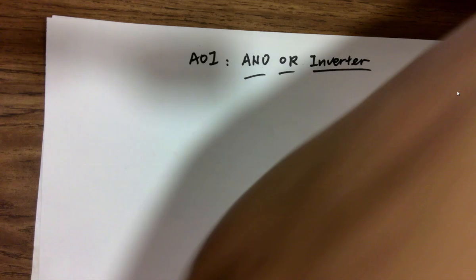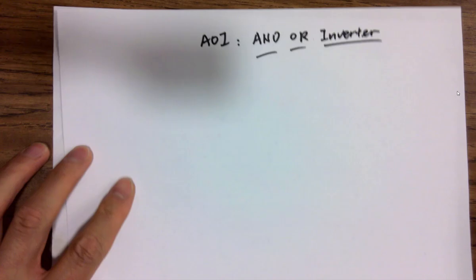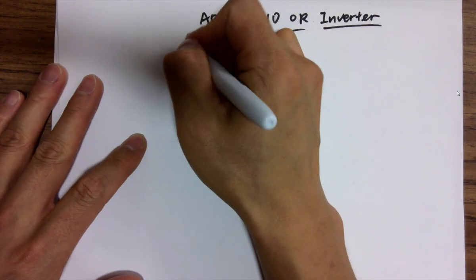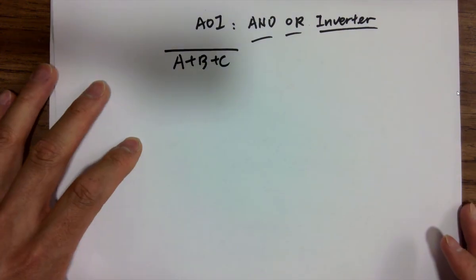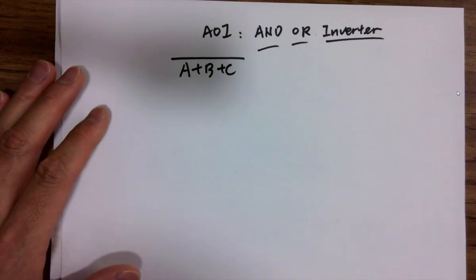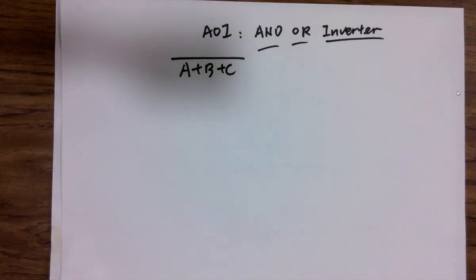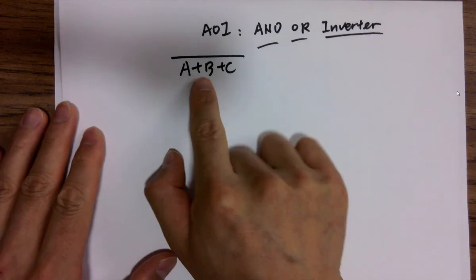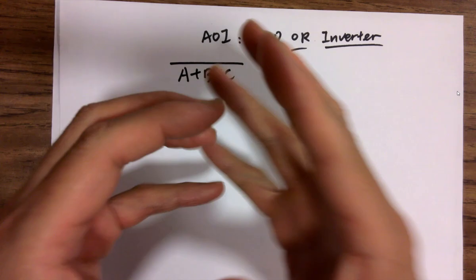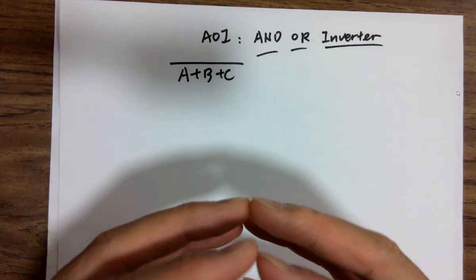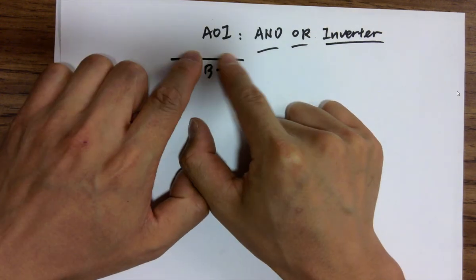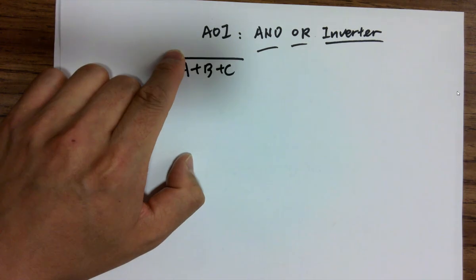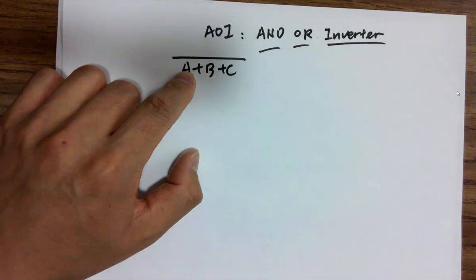Now let's look at more examples. If I have A or B or C, this is pretty simple. How this works: always think about the NAND and NOR schematic. Okay? Whenever you have a logic expression, for the future, the first step is you convert everything to one logic expression and have a universal bar on the top. And then you convert it back. Then you look at that logic and find out the schematic.